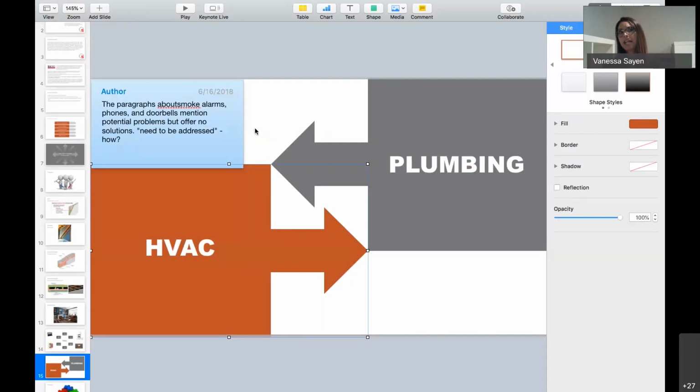Another thing is that HVAC ductwork can transfer noise from one room to another. Having two areas sharing the same duct can transfer noise between them. So if you have a private conversation here, most likely you're going to hear it, even if you already isolated your walls. If you're sharing your air conditioning duct, that noise is going to travel through it.